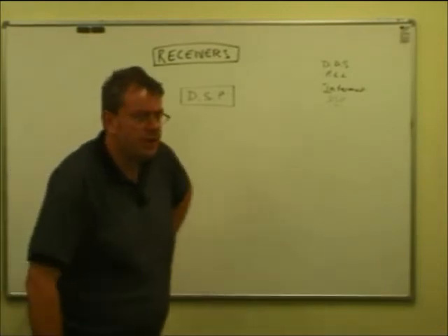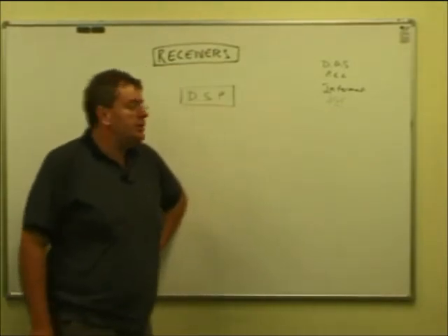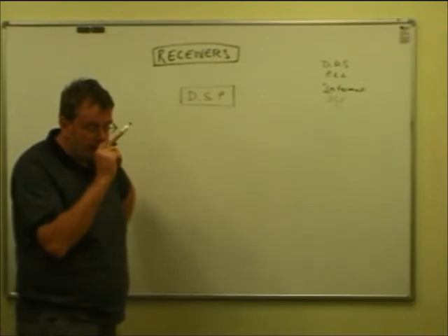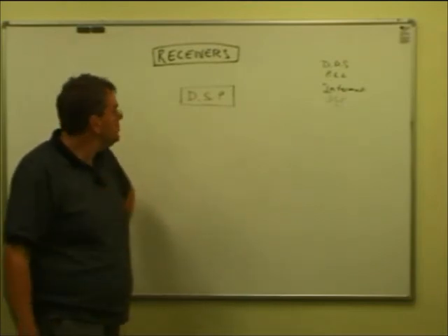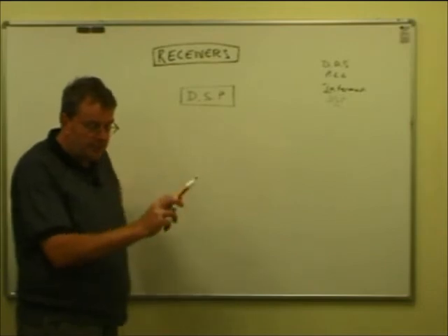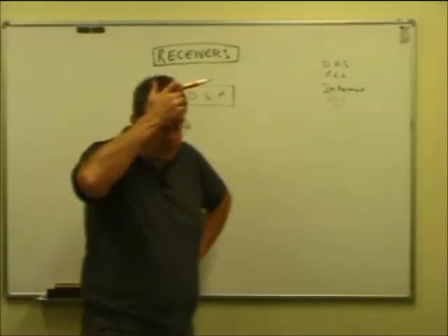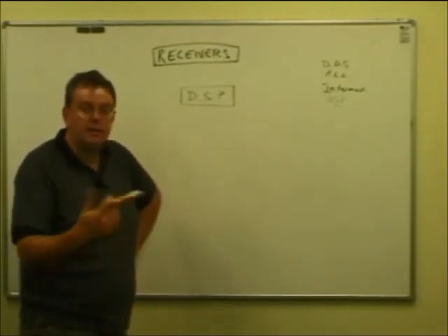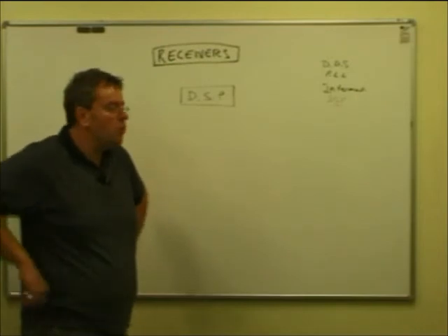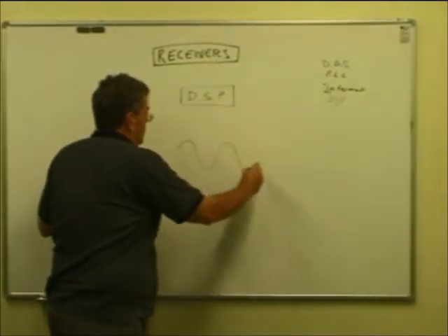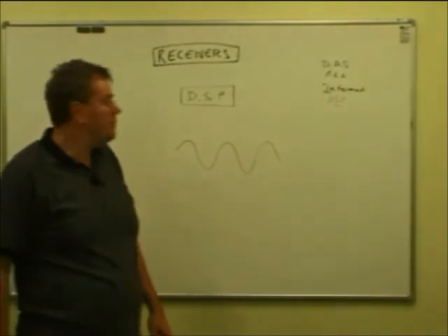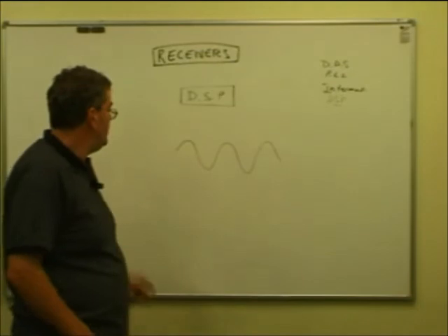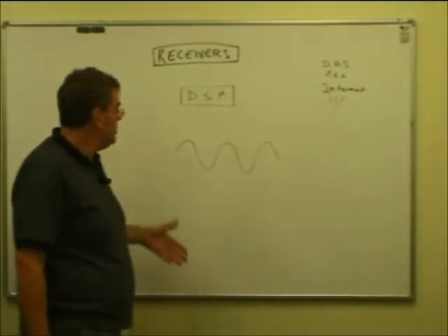Digital signal processing is, we're not going to go into any details because this is a huge area in its own right. Basically what you do is, after the intermediate frequency amplifier, the signal is actually analysed by a computer-based system. It can be done at sound, after it's been converted to audio by the demodulator in an SSB system or something like that.